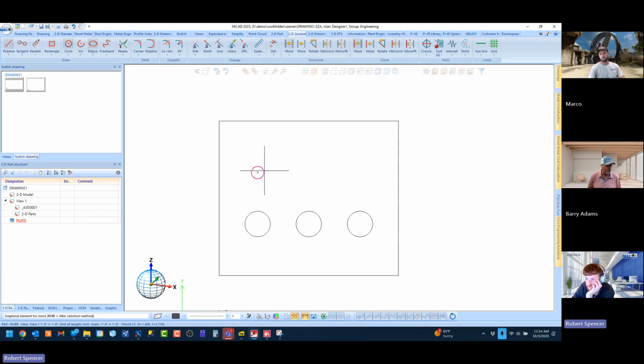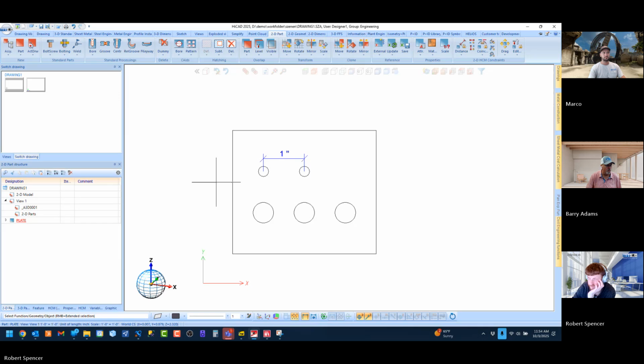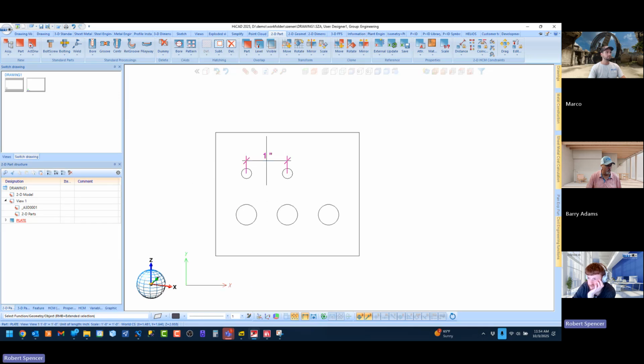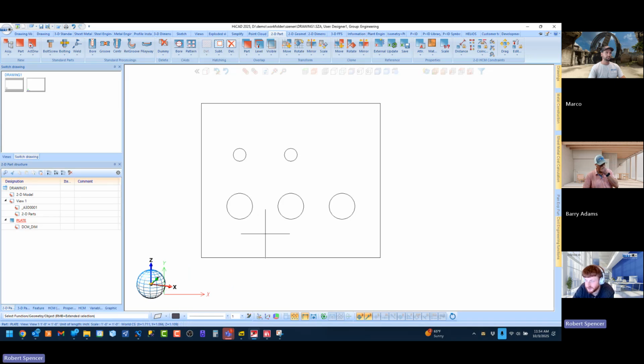If you took this and cloned it and made it 0.8 accidentally instead of that, we do have in 2D part distance constraints where you could say, I want this to be 1 instead. And it'll make that move for you. It's there, you can use it. But for the most part, you're doing 3D work, right?